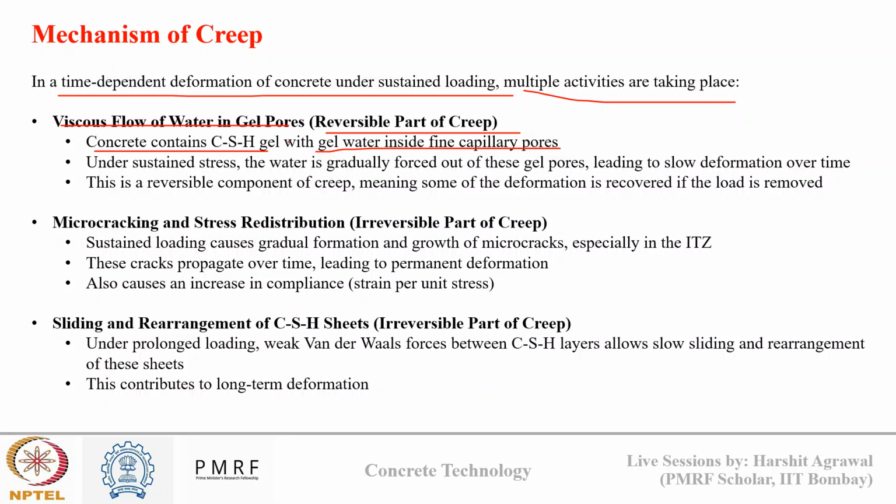Under sustained loading, the water is gradually forced out of the gel pore. So the water which was inside the gel pore will gradually be forced out, and the sustained loading leads to slow deformation over time. This is the reversible component of creep, meaning that some of the deformation can be recovered if the load is removed. This is due to the movement of gel water under loading.